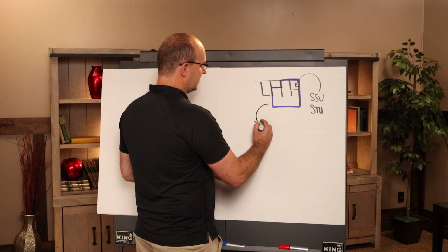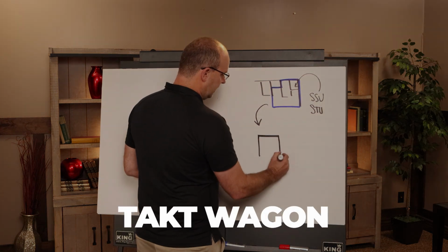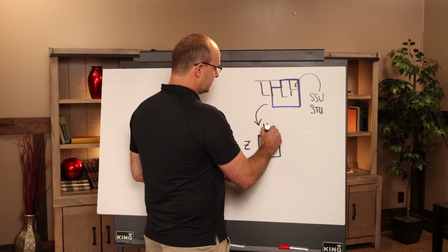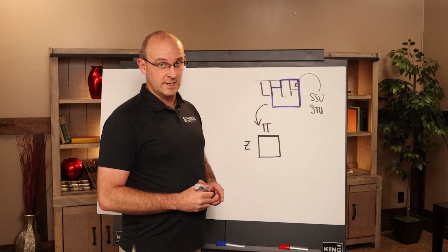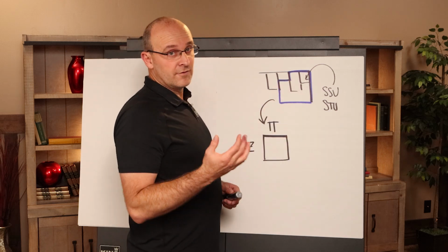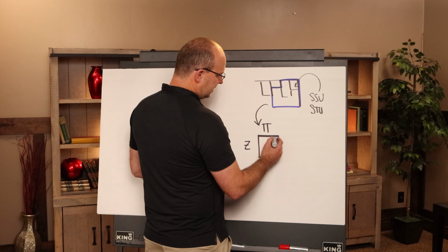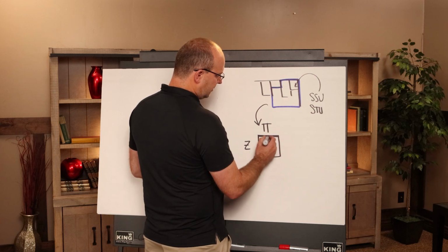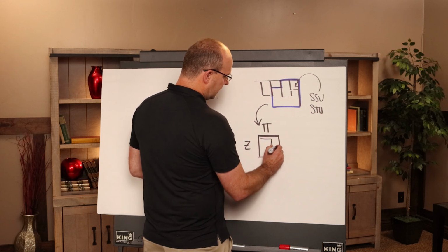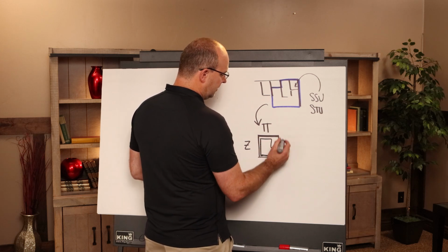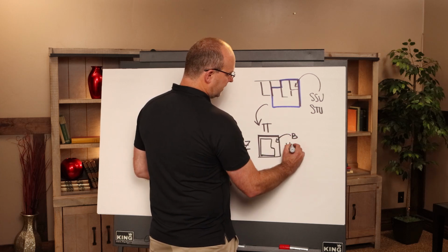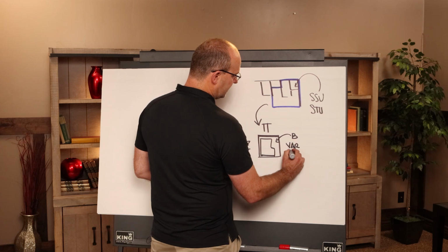That then gets translated into what's called a takt wagon. This means how much work you can get done in a zone in a certain takt time. The takt time is there for a rhythm. So if there's work to be done, let's say that currently it's framing, for instance. Let's say the overall takt time was 3 days, and it takes 2.5 days to get the framing done. You also have some buffer time that will absorb any variation and any productivity loss.